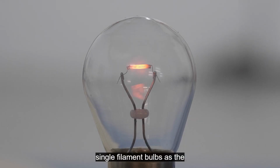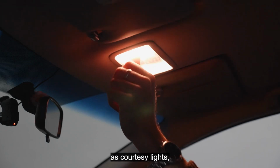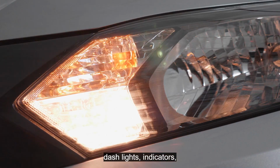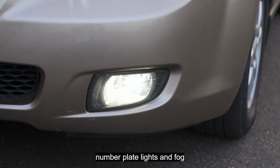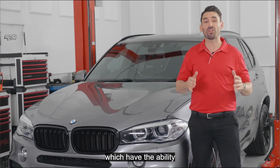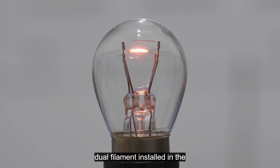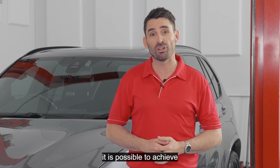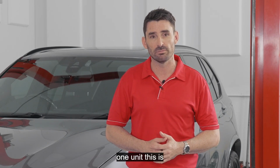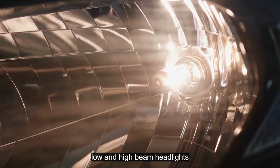Single filament bulbs, as the name suggests, utilize one filament to produce light. These bulbs are generally used in positions such as courtesy lights, dash lights, indicators, reverse lights, number plate lights, and fog lights. There are some bulbs which have the ability to function in more than one way. These types of bulbs generally have a dual filament installed in the glass envelope. By adding another element to the bulb, it is possible to achieve two different light outputs in one unit. This is useful in applications such as stop tail lights and low and high beam headlights.